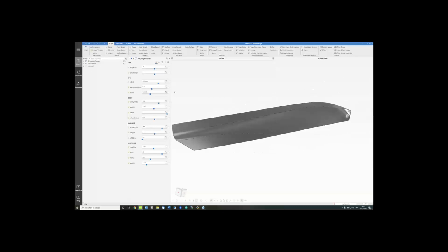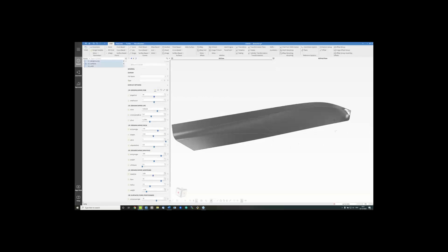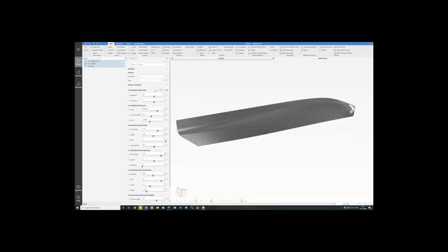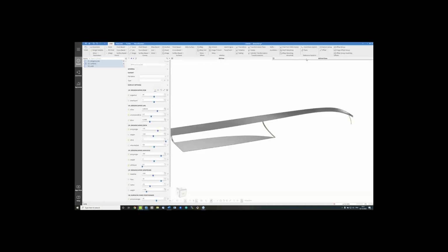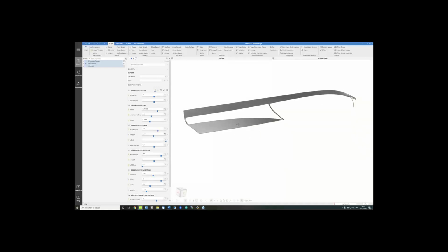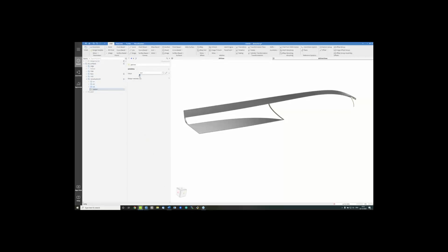And like Marcus already mentioned earlier, the way most of these surfaces are generated in CAESES is by means of a meta surface. That means that starting with the more simple surfaces, maybe like flat of bottom or this ruled surface here, starting as a flat of side and then moving all the way around. Apart from those two, we have 3 main meta surfaces in that model, which are defined by parametric definitions of a section, which is then swept in space.